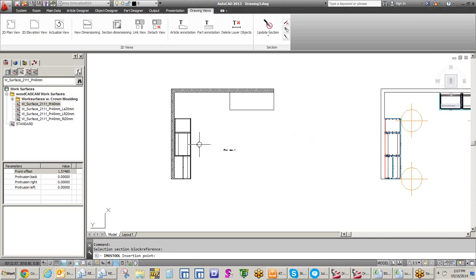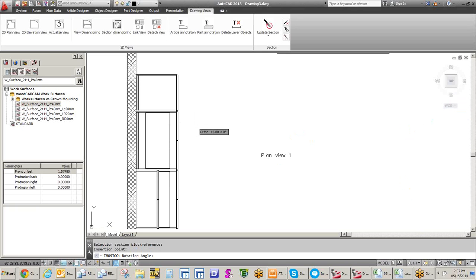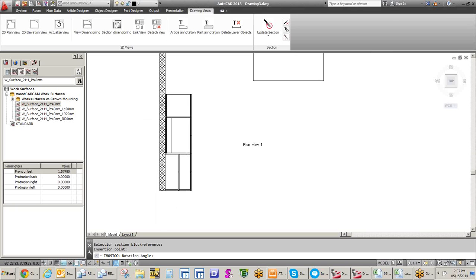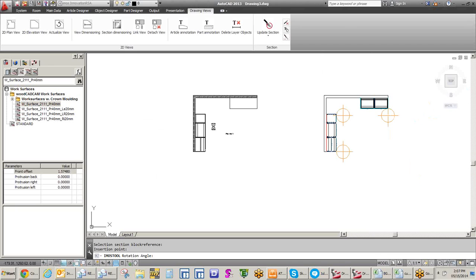So we just select a cabinet on that view, and we set it so that we've got our arrow pointing towards that elevation. Again, it does take just a couple of moments for it to generate the elevations and stuff as well. And so you just got to kind of be patient and talk a little bit and zoom in and out. But once they're created, they do a really nice clean job. And so now we have that, and you want to keep it far enough away so we don't have any conflict of the actual dimensioning. Again, labeling that view as well.